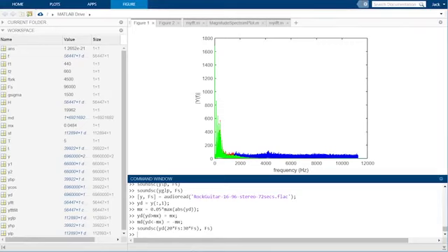This tends to create a lot of power in high frequencies due to the introduction of the very sharp changes to the signal that we create when we clip it, and it also tends to suppress lower frequencies. So we can see this if we look at magnitude spectrum plots.